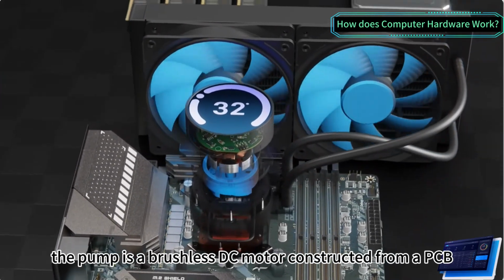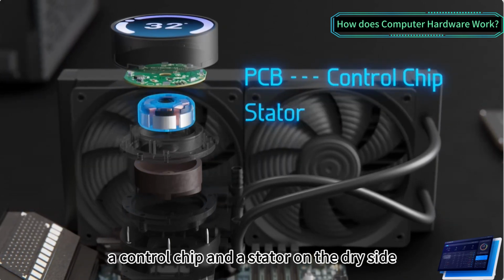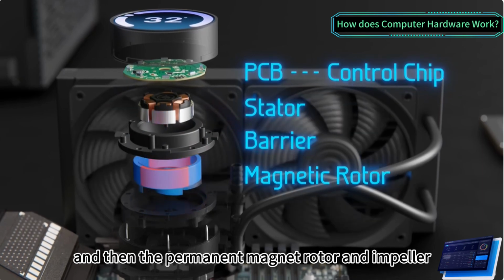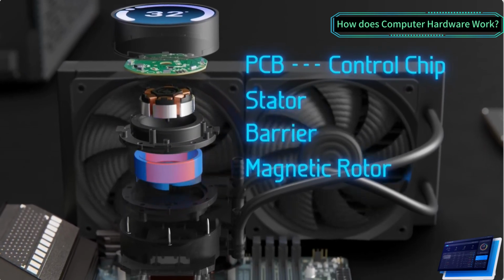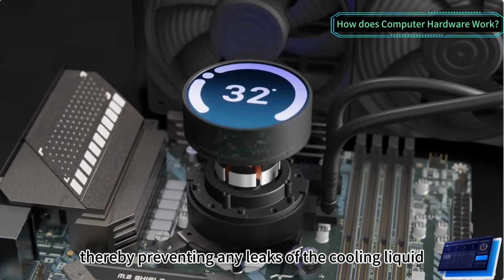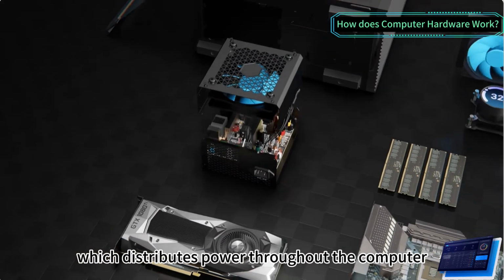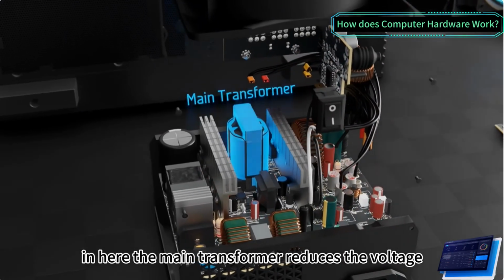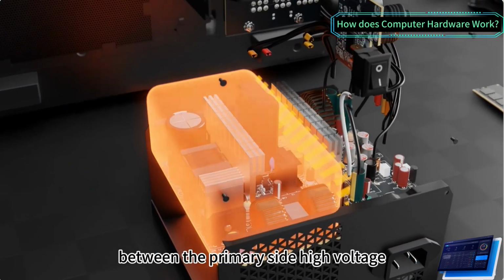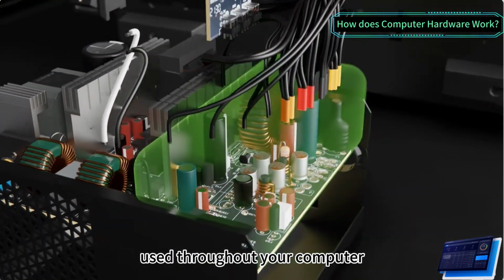The pump is a brushless DC motor constructed from a PCB, a control chip, and a stator on the dry side, a barrier in the middle, and then the permanent magnet rotor and impeller on the liquid side. There's no mechanical connection between the rotor and stator, thereby preventing any leaks of the cooling liquid. Let's move on to the power supply, which distributes power throughout the computer. In here, the main transformer reduces the voltage and bridges the isolation boundary between the primary side high voltage and the secondary side lower voltages used throughout your computer.